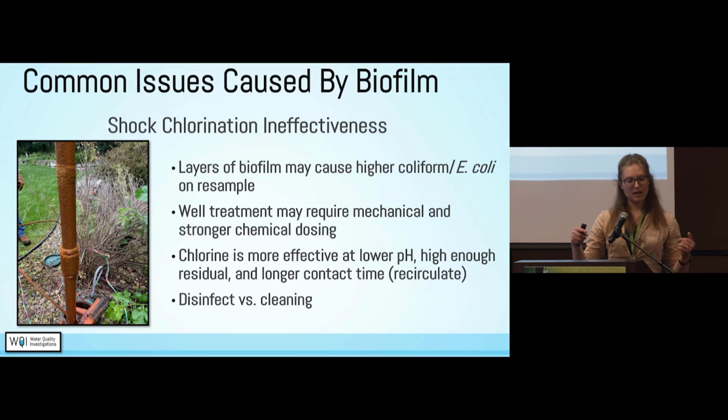Remember when I showed you how biofilms are formed? It's not just one type of bacteria, it's not just one layer, it's all different kinds of substances. And so when you basically strip a layer, you might have a higher coliform count after a shock chlorination. And that's because those bacteria on the next layer are now exposed.